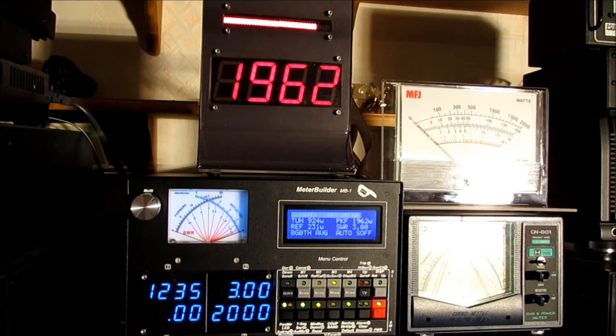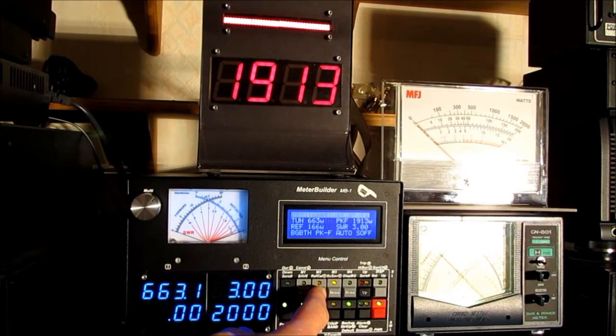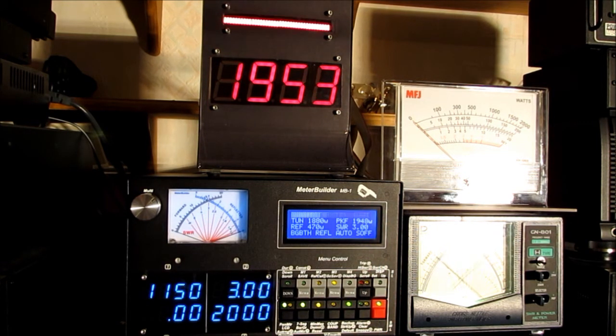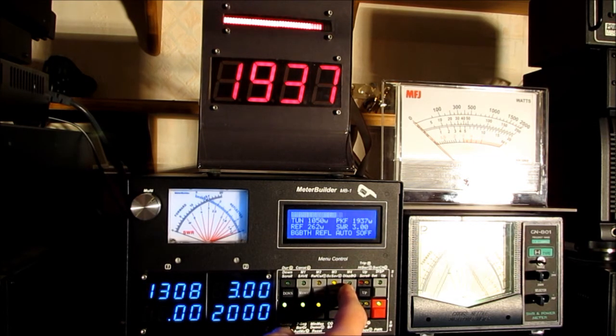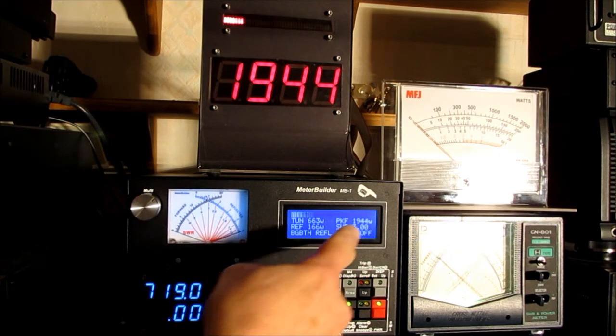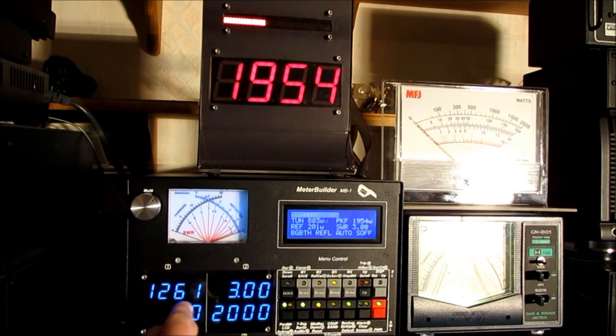Okay, so we've basically talked about Automax. We'll leave that on. I can display peak forward, reflected, and if the portion of the bar graph is obstructed by the display, I can always force the current full-scale bar graph value with a long push of one of the menu buttons. It's also possible, as we saw before, to configure one or more of the 7-segment LEDs with configuration information. So the value that I have displayed here could just as well be displayed in one of the 7-segment displays as well.